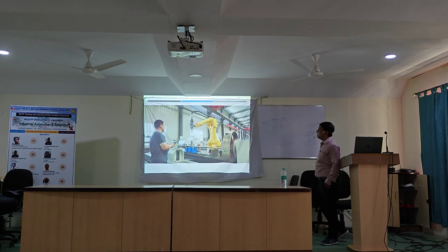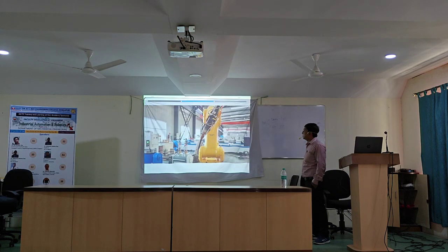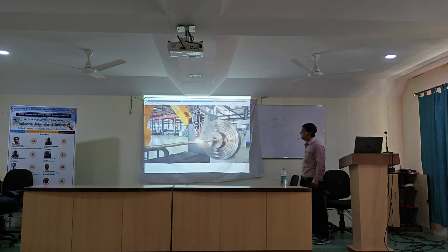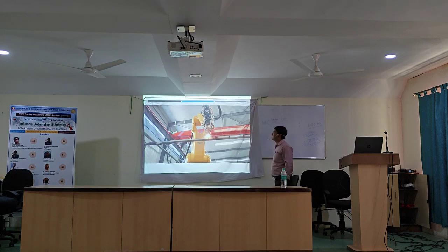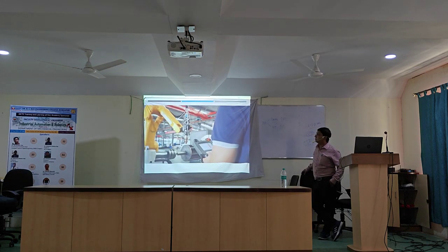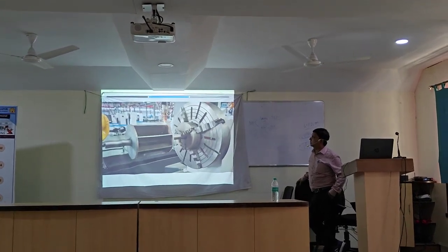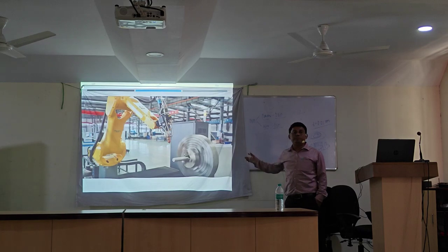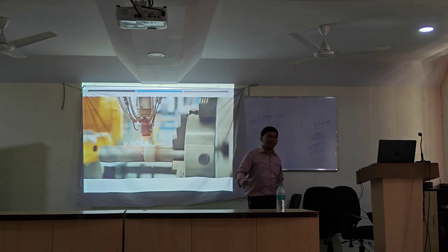So this is typical robotic additive manufacturing used in the industry. This is a powder DED process. Over the existing component, some repair work is done by the powder DED process. Basically, it is the extension of the laser cladding process. This powder DED is the extension of laser cladding. Laser cladding has one or two layers, here multiple layers.